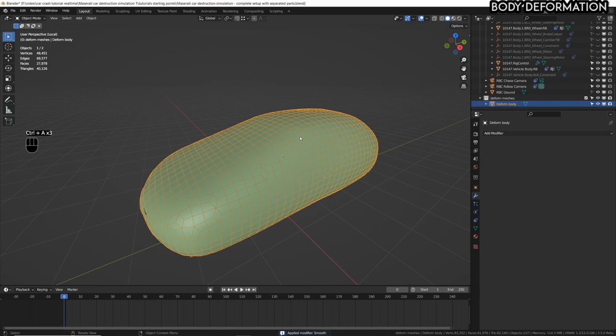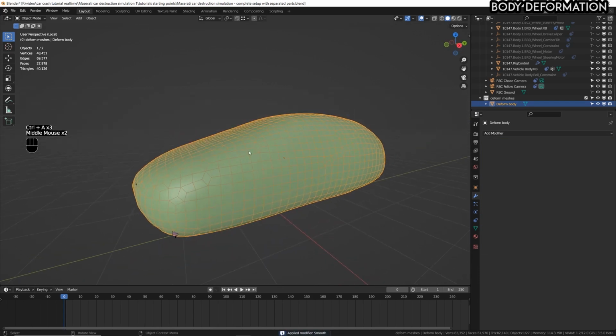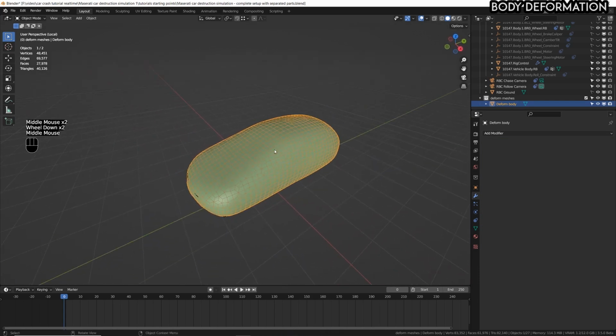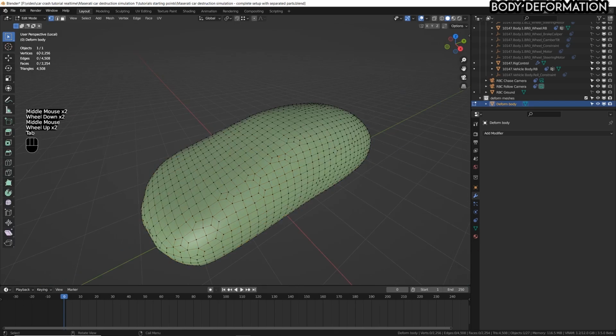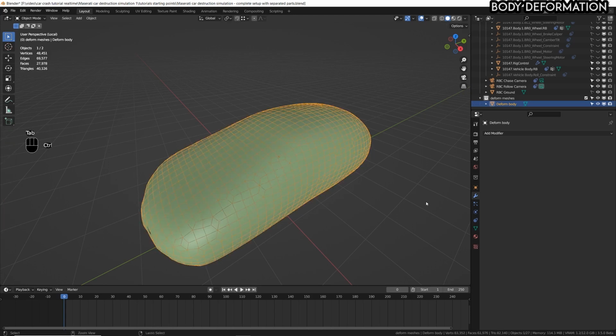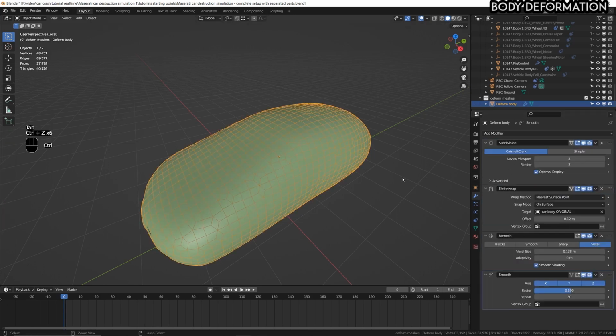Now we can check immediately the amount of geometry, of vertices, that we have created for this mesh. So enter edit mode, and you can see up here 2256 vertices. Well, I would like to stay more like 2000 instead of 2200. So let's go back, Ctrl Z many times until I get back all my modifiers, and we can adjust it by playing again with the voxel size. So in this case, I'm going to increase it a little bit, just a little bit like this.